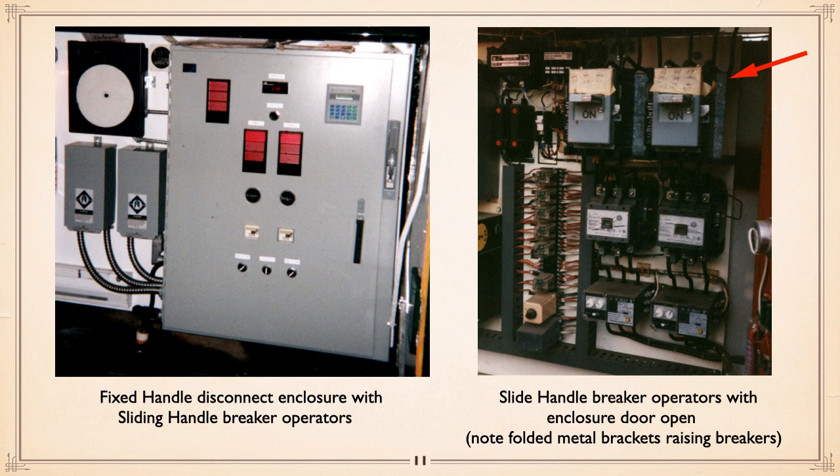They can be padlocked off, by the way. That little thing on the handle to the right actually will pull out and you can padlock it if you have to. We'll get into that issue of disconnect or padlocking in a minute.